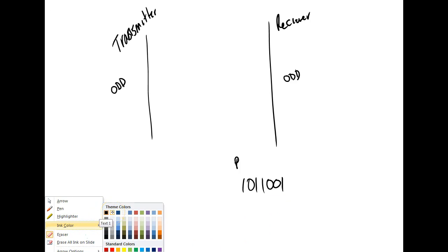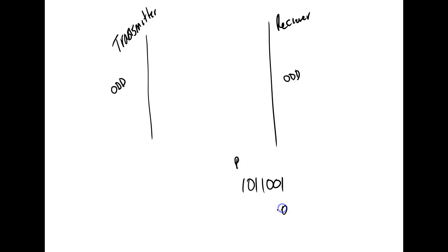So 0 is considered an even number, right? 0, 2, 4, 6, 8. So you're right. If I was to do this, which is a control code, by the way, then my generator would set the parity. Then this guy over here receives it. That'll make that odd parity, right? Yes, because that's what we have up here. We're doing odd parity right now.